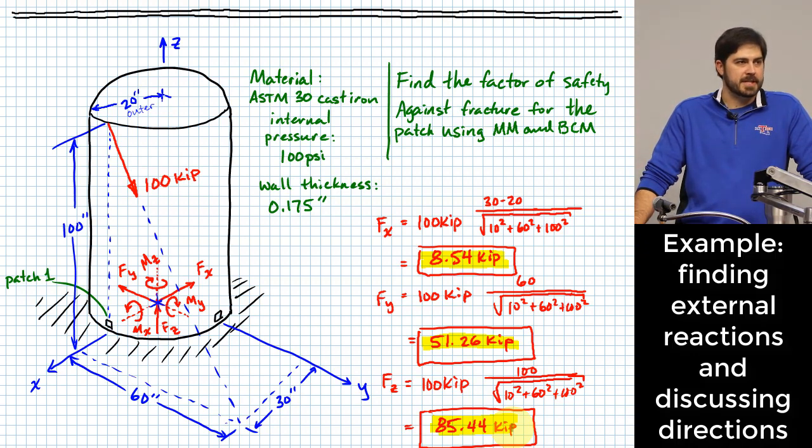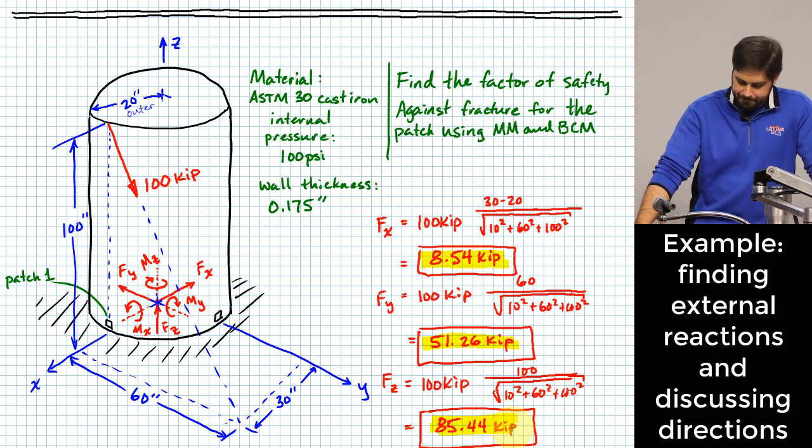We're going to assume that the tank is internally supporting hoop stress that might happen due to the internal pressure. Well, really the hoop stress and the axial stress due to the internal pressure. We're assuming that the structure of the tank itself manages those things.